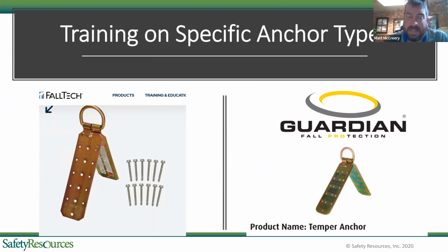But you have to be, they give you very specific shear angles, so they have to be installed correctly and in line with where your people are working. So that's why when we were doing the low slope stuff, we talked about, listen, if you're still using these types of anchors, you're setting yourself up for some failure. Roof carts and things like that are much more effective.